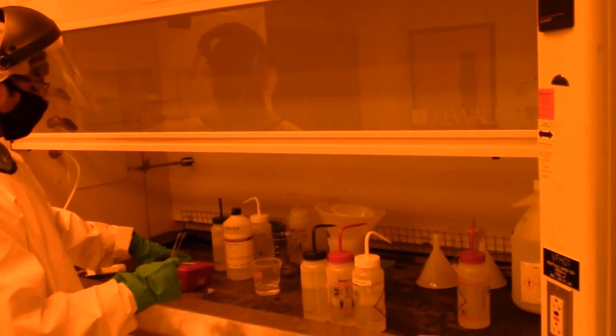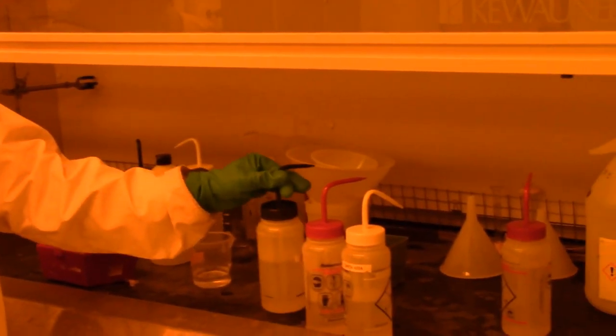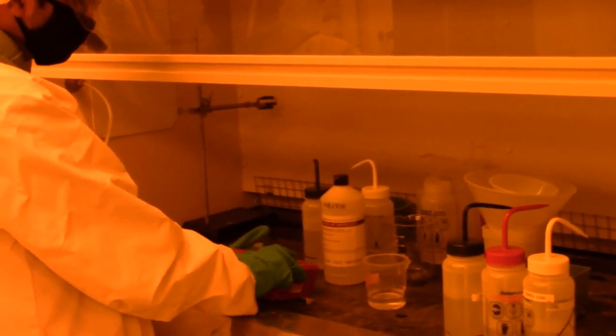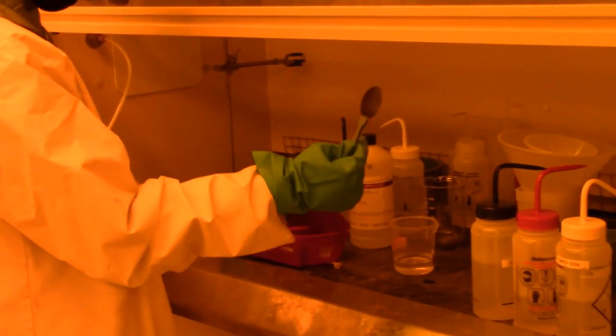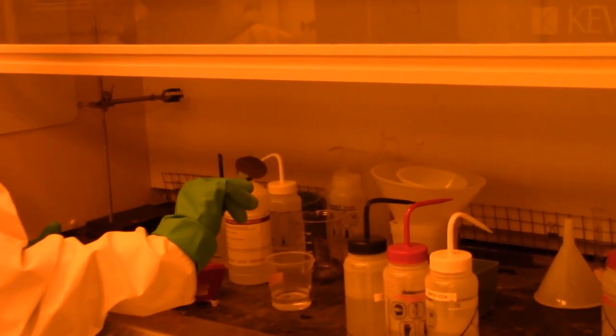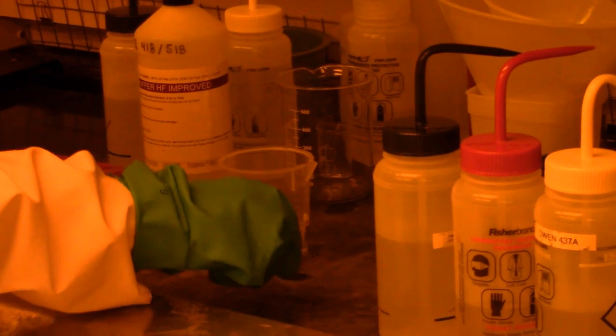The way to go about doing a hydrofluoric acid etch is to make sure everything is ready. Have clean water ready in case of any spill. Let's go on with the etch. We'll take the wafer out. The important thing is to make sure that we etch the backside of the wafer, so we'll keep the backside exposed to the top. And once we drop the wafer inside the HF solution, go ahead and start the timer.